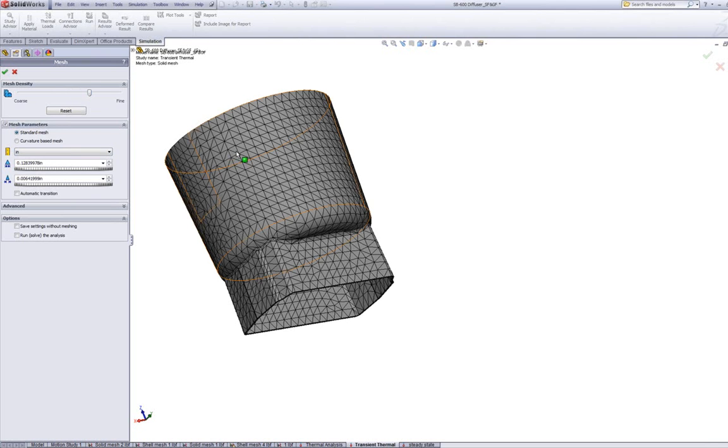This will give you more points of calculation and will also increase your accuracy. Now, you don't want to get carried away with increasing the accuracy on this, just because the higher you get, the more points of calculation, the more time it'll take to run the study, and potentially if you have a lower end system, you could crash out your system and it might become unresponsive.